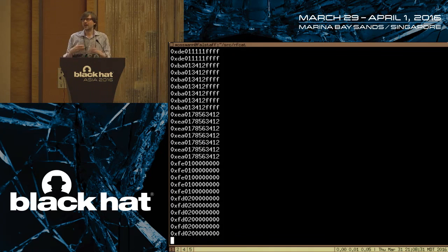It's not a more complicated algorithm like a CRC, but it's only an 8-bit checksum. And it looks like it's just a simple addition or subtraction of all of these things. When I enter in all zeros and then a lock code, which is just 1, I set one bit, and you'll notice that the resulting checksum is FF minus 1. Then when I had a nibble that was 2, the checksum is FF minus 2. So it's probably just a subtraction of all of the bytes in a row.